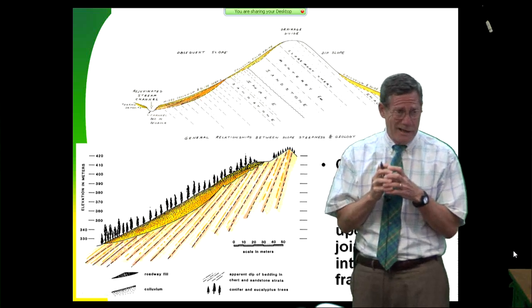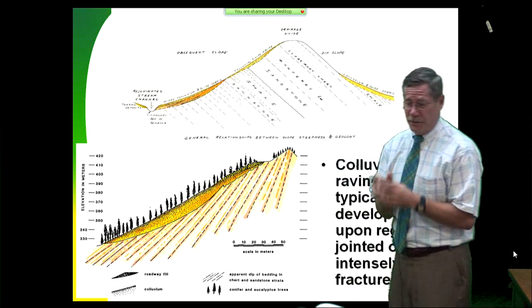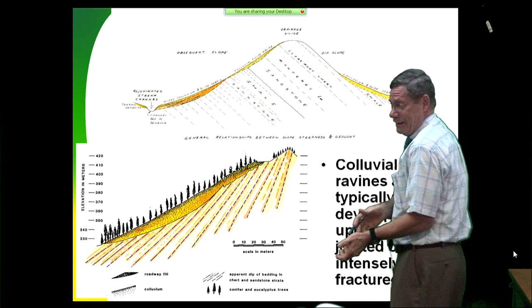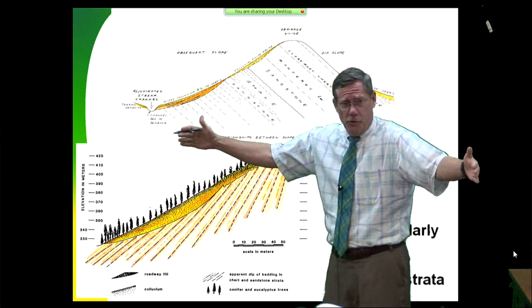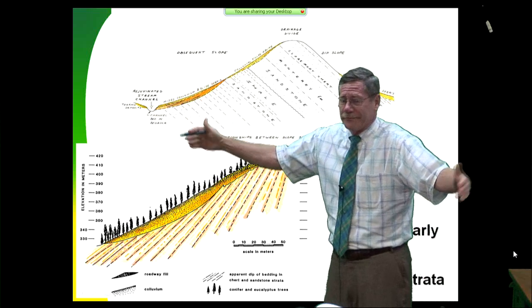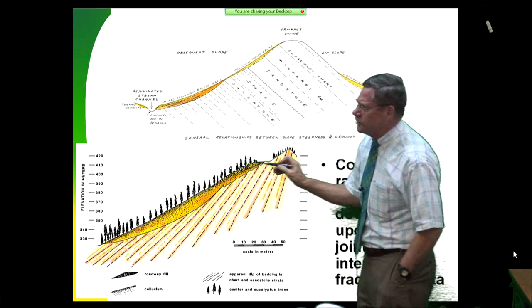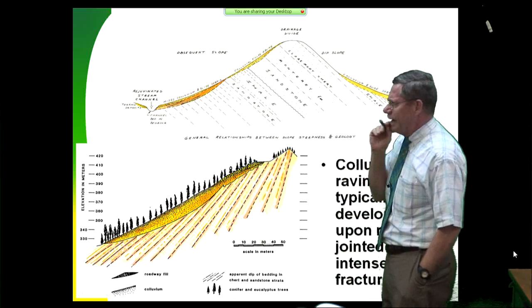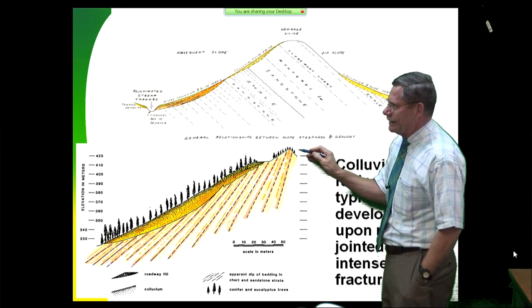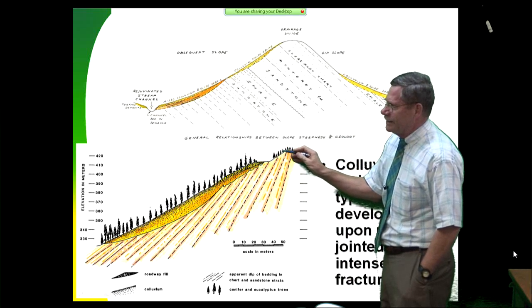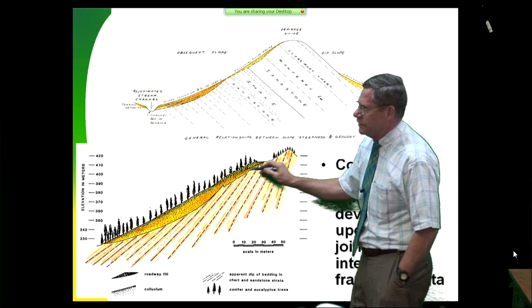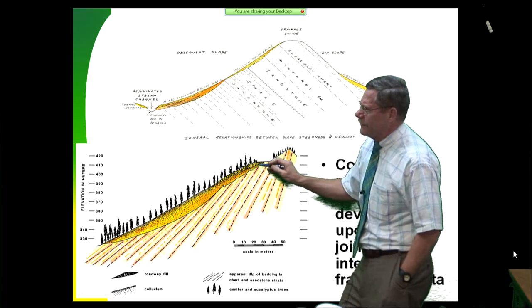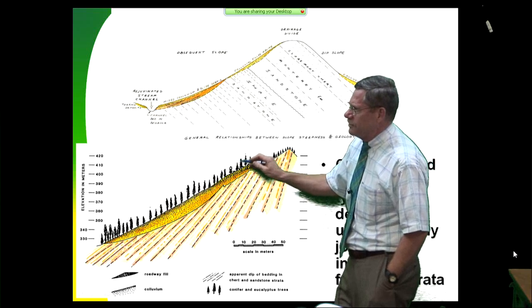It's rock. No cohesion. So if you run water on it out of a culvert, it just erodes like crazy. You get this beautiful vertical hole 47 feet deep. And of course, if you look at the trees now, go back and use my dad's methodology, look at the stunted growth on these guys. They're on the bedrock. There's the highway. Come over on the fill. This is the side cast fill for the highway, put in 1935. And I got pretty nice trees.